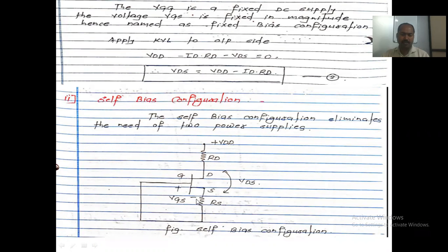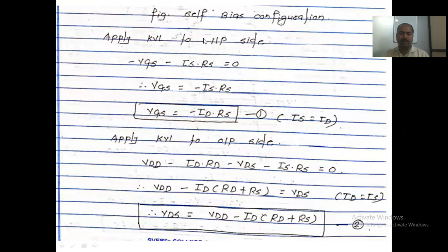Second point, that is a minus. So minus VGS, and then again the second point is coming from here. Current flowing through this RS is IS. So minus VGS, minus of IS into RS, because plus is here, minus is here. This is nothing but the input equation.